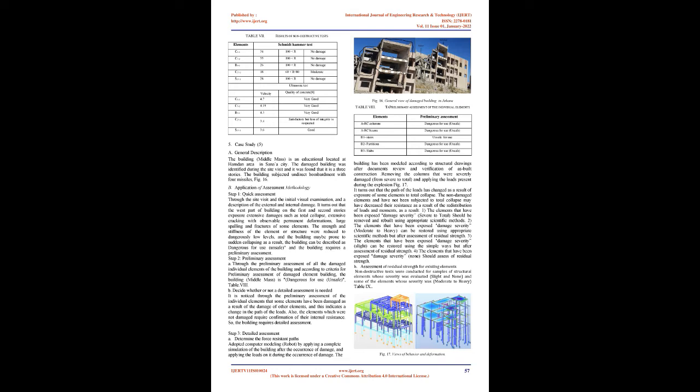However, the strong blast wave that directly hit the building may reduce the resistance and quality of the elements that were not damaged or that were exposed to slight damage. Therefore, the resistance and quality of these elements must be ensured after the damage occurred through in-place tests. Table 6. Preliminary assessment of the individual elements. Assessment of residual strength for existing elements by in-place tests.